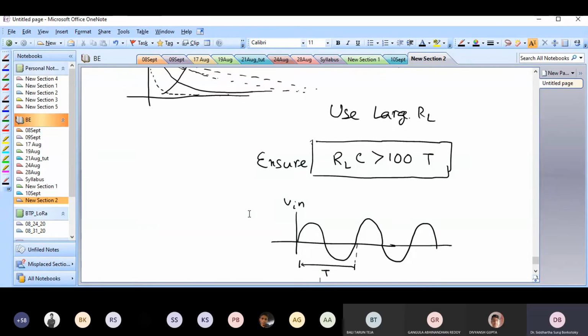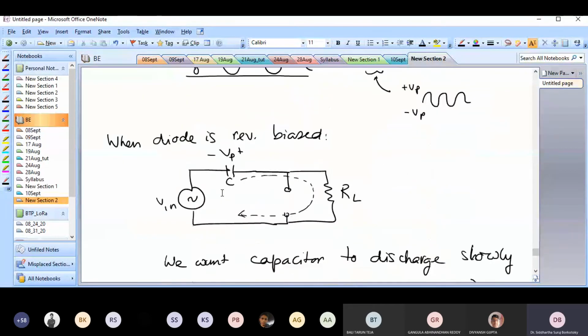So at some point the VP is going to decrease, but at that time again there will be a point at which the capacitor will be able to charge back to its peak. It will lose some charge, but whenever the diode conducts, the capacitor will charge itself back. So basically, the entire idea is that this capacitor is acting as an external battery. I am adding an extra battery in there, and that battery is shifting the entire waveform upwards by an offset of Vp.